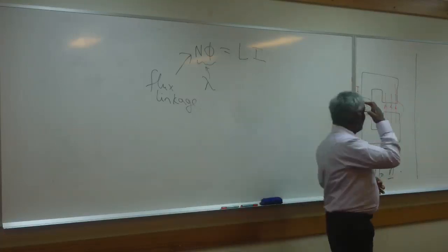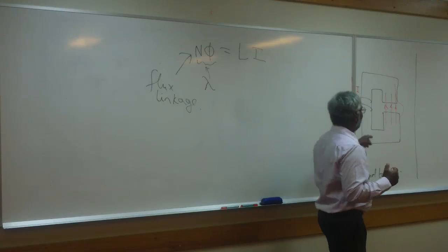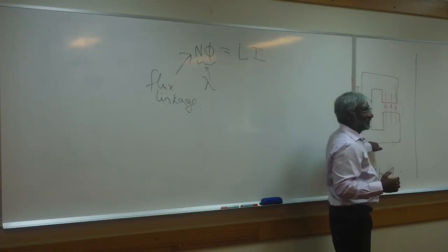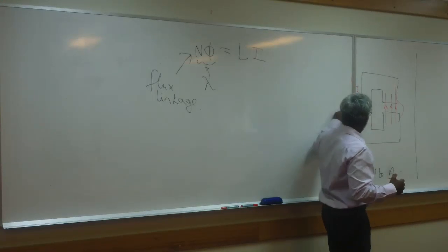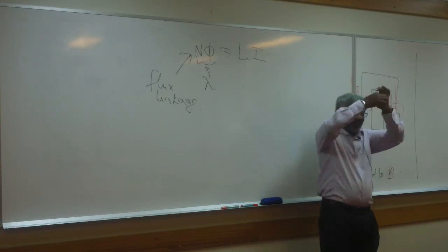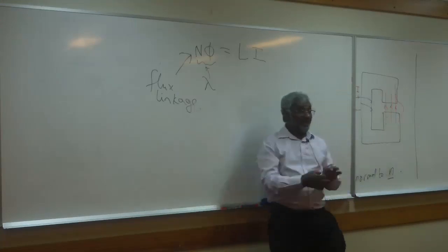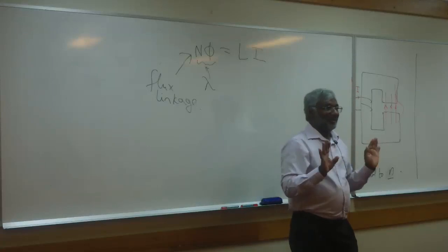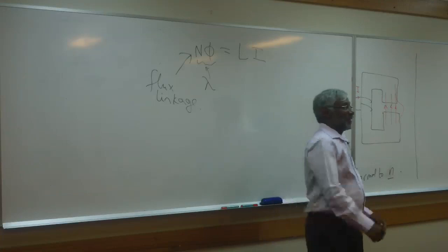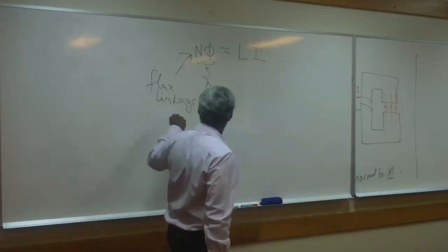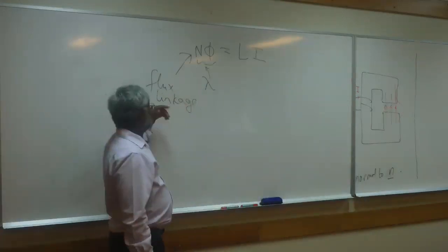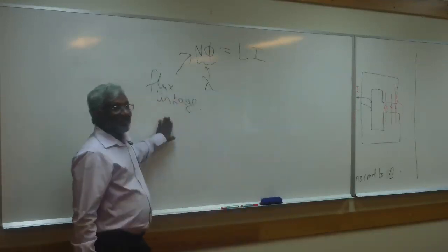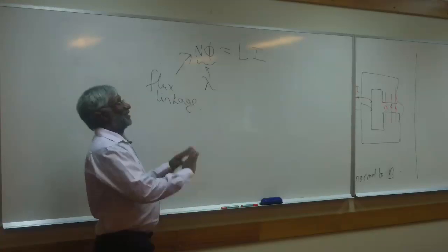So if you think about it, you would see that these red lines are a circuit, and the current is a circuit, and they link. So that's the linkage. If they don't link, then all those things that we talk about would not happen. So it's that linking that gets it to happen. So this is the word linkage, and it's there for a reason. So there's flux, and there's flux linkage. If there's flux without linkage, then there's no inductance.